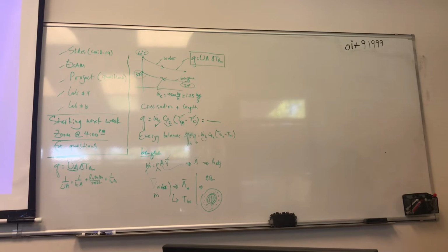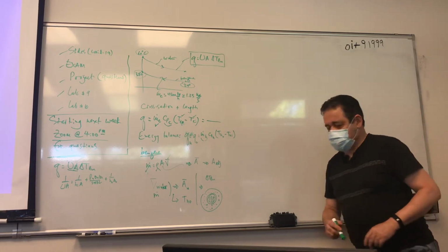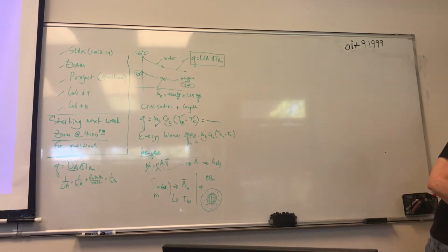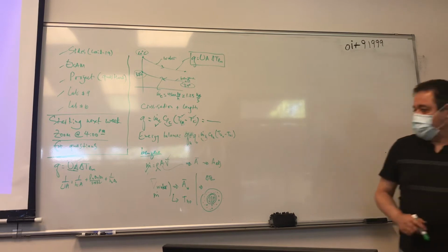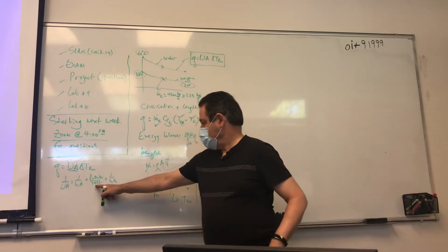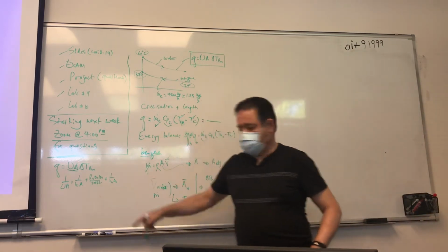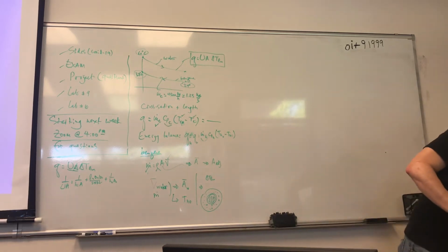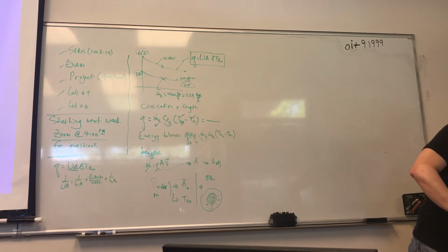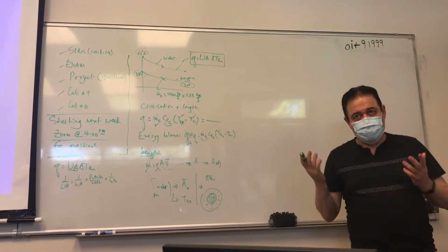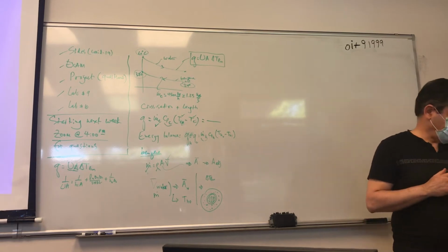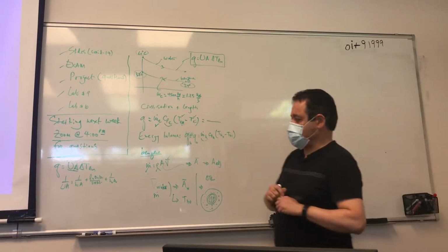So did I write it correctly? There are two missing, you have two extra: 2 pi KL. Well, they have the R_fi over A_i and R_fo over A_o. Those are the fouling, I'm not considering those. You feel free to consider them if you wish, but that's equation 11.5.